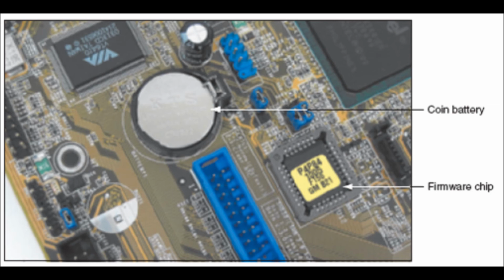The motherboard ROM BIOS serves three purposes. The BIOS that is sometimes used to manage simple devices is called the system BIOS. The BIOS that is used to start the computer is called the startup BIOS, and the BIOS that is used to change some settings on the motherboard is called the BIOS setup or CMOS setup. These motherboard settings are stored in a small amount of RAM located on the firmware chip, and are called CMOS RAM or just CMOS.